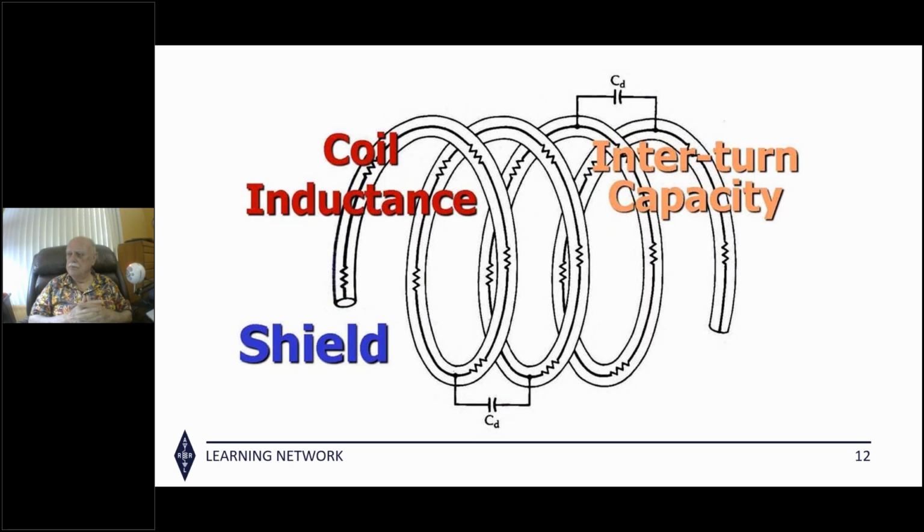Next, any particular coax that should or should not be used for a Balun? I don't see any reason why any coax shouldn't be used. Starting at the bottom, like for 6 meters, I've used RG58, not great coax, but okay if you don't run very much of it. I've used Mini 8, and that works quite well.